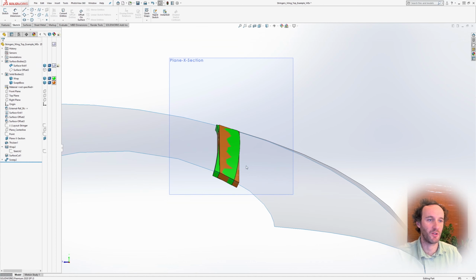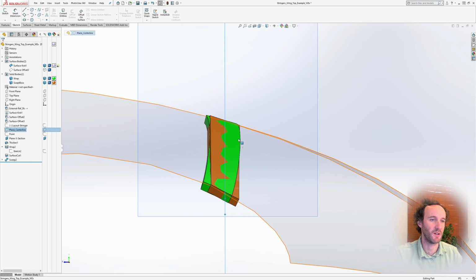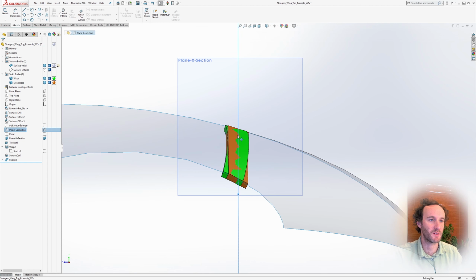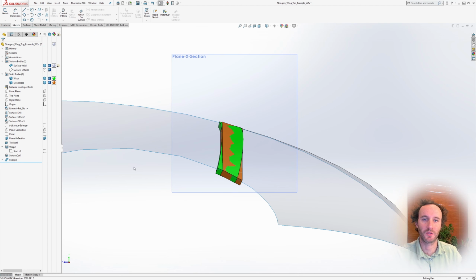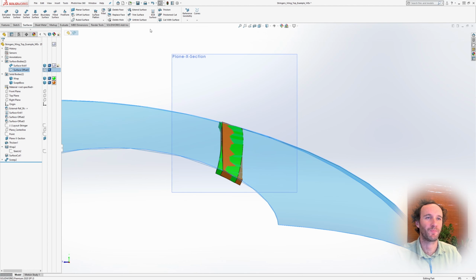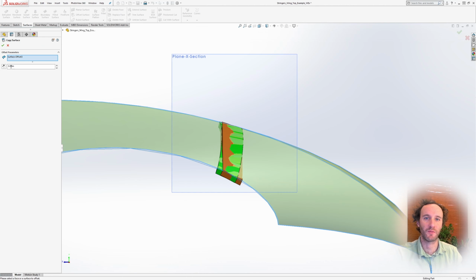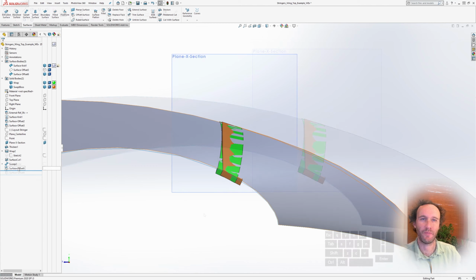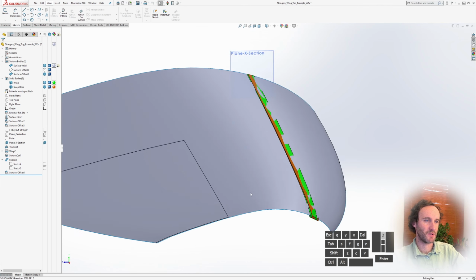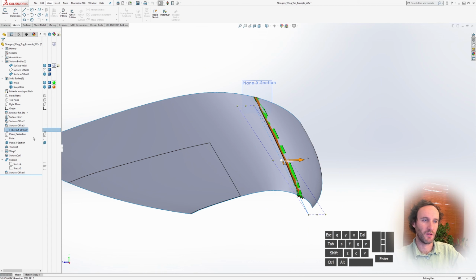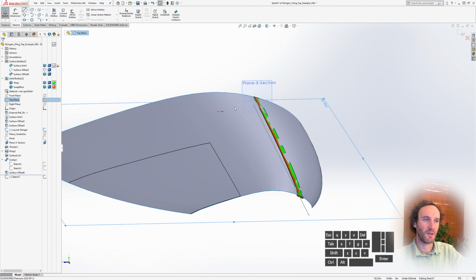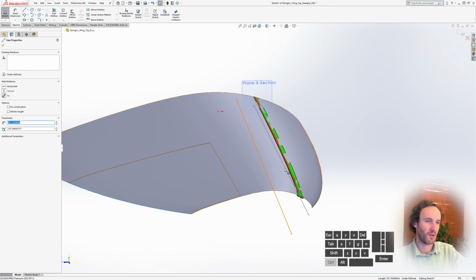One thing we can do to get something with the same center line as this swept boss, but to twist with the normal constantly in the surface's direction, is this. First I'll create some copy surfaces of the outer surface there. And with this surface, we're going to take the layout and make another sketch in the top plane, the line that's parallel to it.